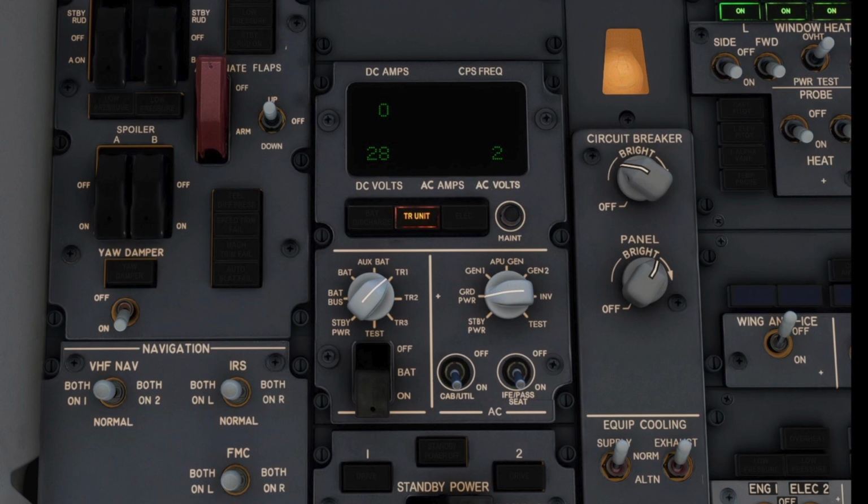There is an exception however, the crossbus tie relay opens when the glide slope is captured, when using the Autopilot Flight Director System and approach mode. In this case, that would result in DC bus 1 being unpowered as soon as the glide slope is captured. If used, it would cause the autopilot to disengage and the flight directors to be unavailable.